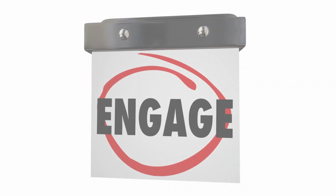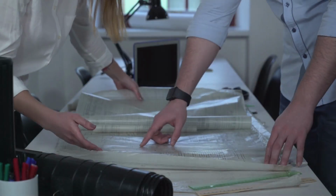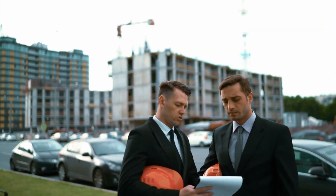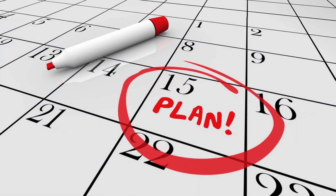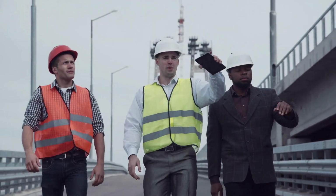In order to obtain prior consent from a local authority, a developer or contractor should notify them of the proposed works well in advance of the planned start date. Typically, this should allow 2 to 4 weeks for preparation of the Section 61 application, then a further 4 weeks or 28 days for the local authority to process it and raise any queries.